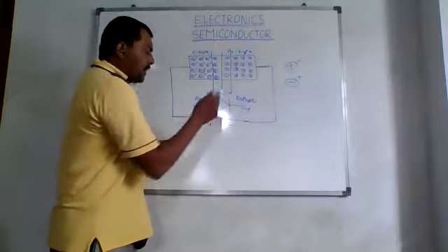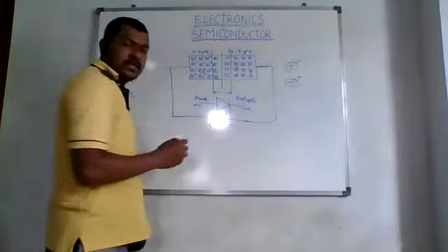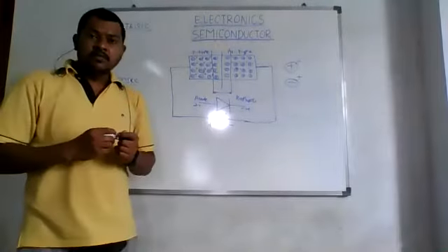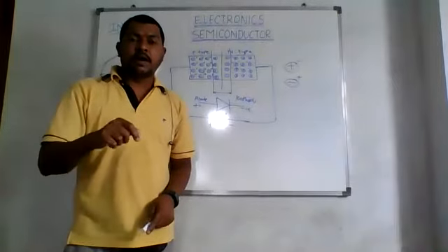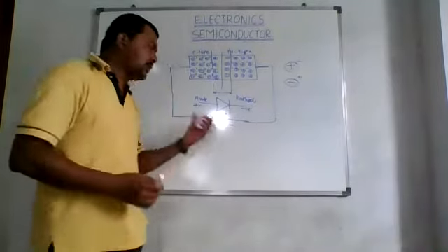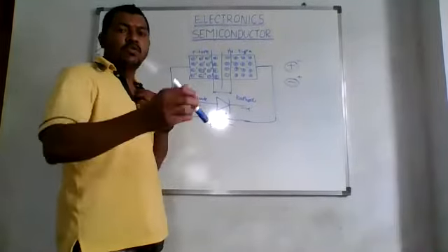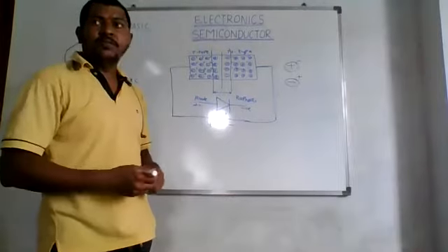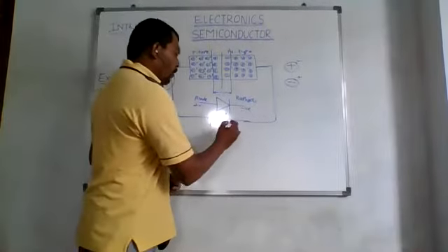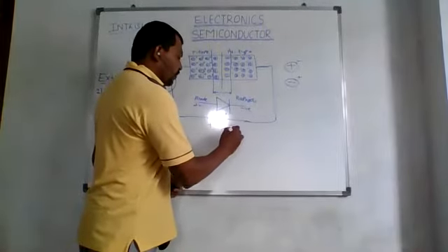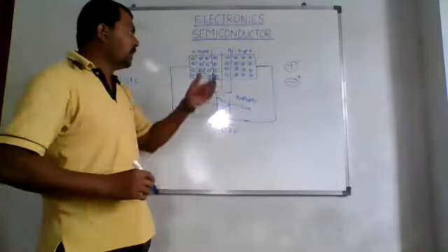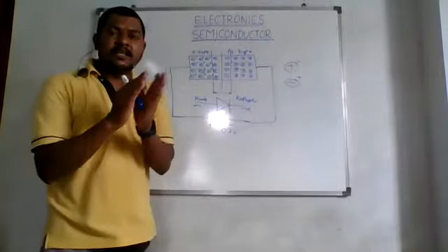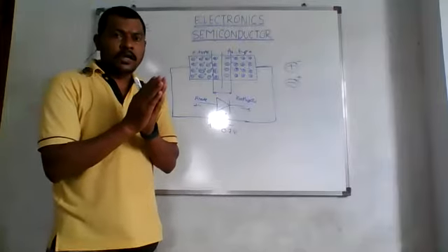So as you increase the voltage like this, why have I drawn this arrow? It is a variable power supply, right? So when you vary this voltage from 0 volts to certain volts, around 0.7 volt for silicon, this depletion layer gets dissolved, right?